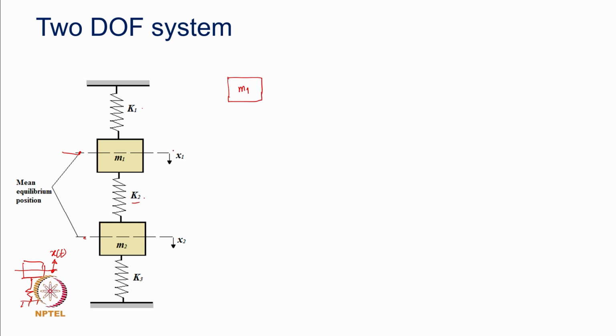The motions are shown as they are, I mean the degrees of freedom are identified as x1 and x2. Without any loss of generality, I can assume that x1 is larger than x2. For the sake of getting all the forces recorded on this mass on the free body, stripped from the surrounding, this body will have this connection point to the spring at the top and that one at the bottom. So, those are the only two connections of it with the surrounding, isn't it?